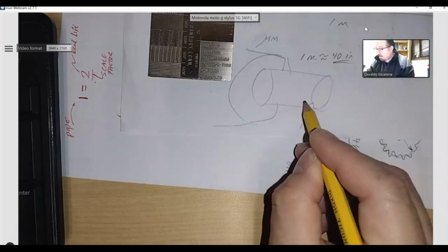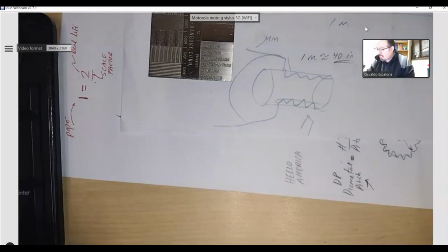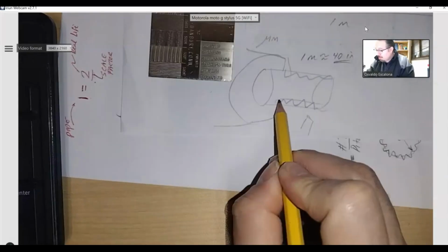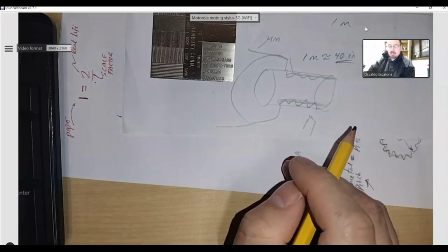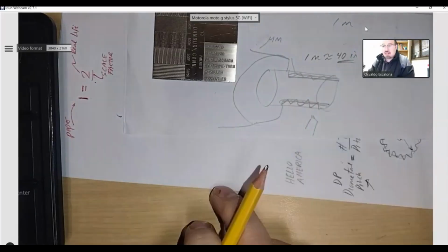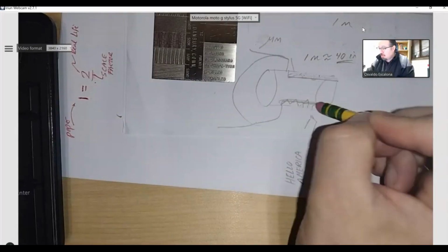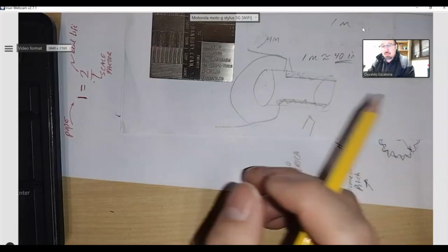The first one, you take a bunch of material, as much as possible. That's the rough turning. In the second one, you go back and you take away a little bit less material. Let's call it semi-finish turning. And then you go back again, finish turning. So now it has the right size. Oh shoot, I need to decrease my tolerance because I have a special application.